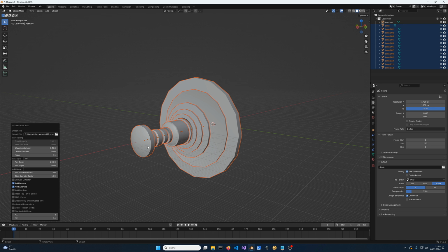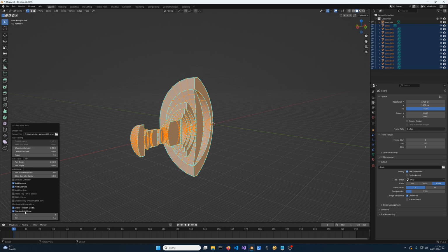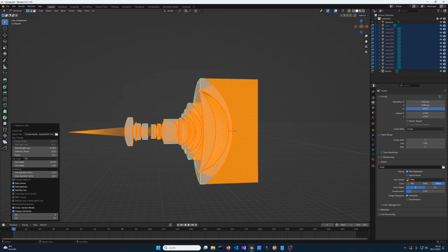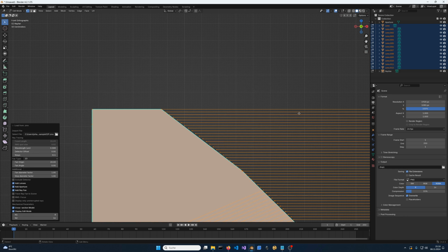So if we have 13 meshes at a high resolution, this can lead to quite a significant processing time, maybe half a second, which would be noticeable in the performance when looking at ray tracing, which has nothing to do with the meshes. So for looking at the lens in a cross-section model, adding a ray fan, the larger number of rays, and looking at the focus like we do here, the resolution of the meshes isn't important at all, because this internal sequential ray tracer independently traces to the precise curvature of the surfaces, the non-segmented surfaces. So whether you have a really high resolution or a really low resolution, the intersection points of the sequential ray tracer are exactly the same and are not impacted by this in any way.